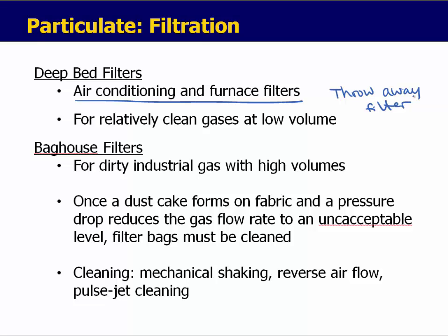This is why these are most common for households where a fairly small volume is passed through. For larger buildings or industry, baghouse filters are more common. These are used for higher volume flow-throughs. Once a dust cake forms on the fabric and a pressure drop reduces the gas flow rate to an unacceptable level, filter bags must be cleaned. Cleaning can either be performed mechanically, by reversing the airflow, or by doing a pulse jet cleaning.